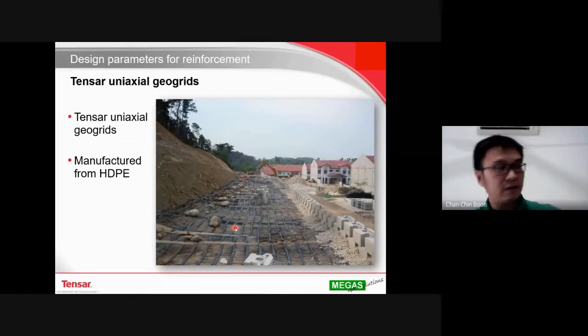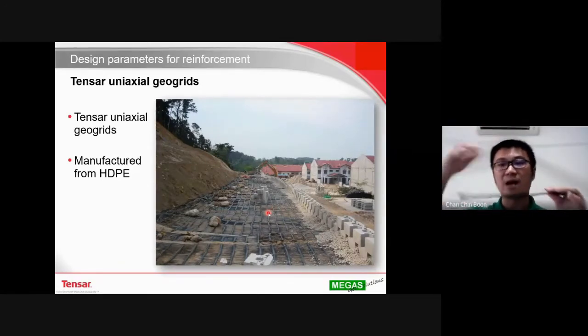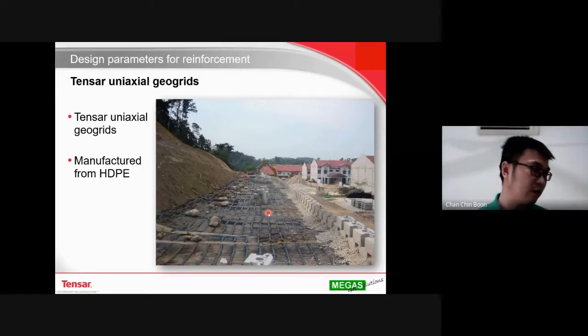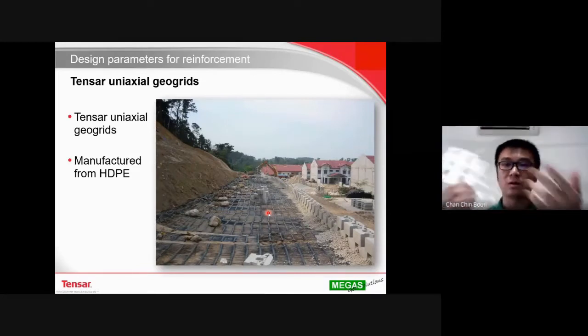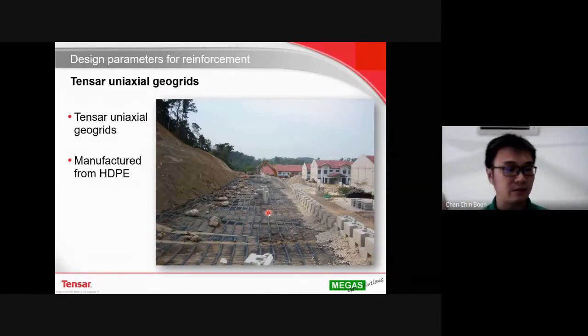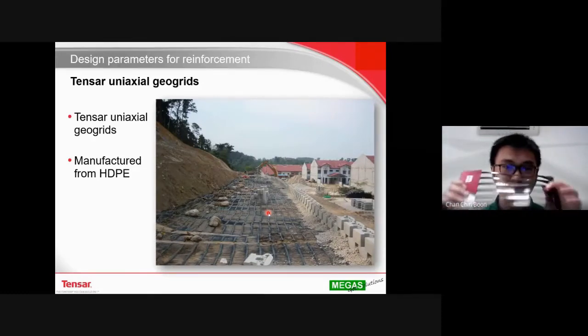so there are different types of geogrid available in the market. For example, what we can see in this picture is a geogrid like this, which we call an HDPE geogrid using a punched and drawn manufacturing technique. Okay, and there are some other geogrids available in the market as well. For example, we have this kind of polyester geogrid. Okay, it looks very flexible, and the joints can move. Or we have this type of welded joint geogrid, or this kind of woven geotextile, and so on. There are different products, but today we will focus on this HDPE geogrid because this is something I would like you to know more about today.